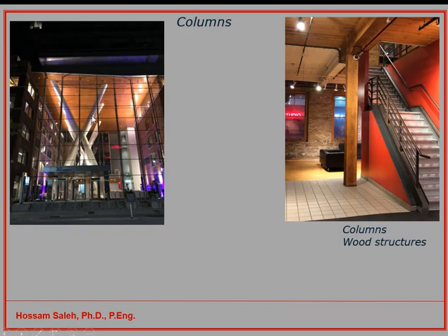In this entrance, you can see there are some inclined columns as an architectural feature in the building. Now, we can argue about these columns. Are they load-bearing columns or just a decoration inside the building? If these columns are load-bearing, the architect has to consider that within the ceilings there should be a tie or another member which will support the columns in the horizontal direction, because there is a component of this column force in the horizontal direction.